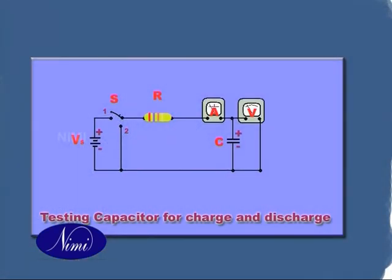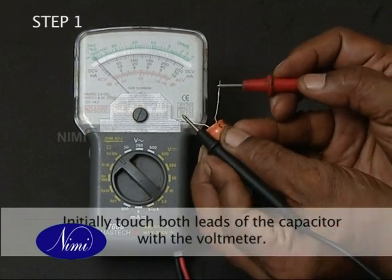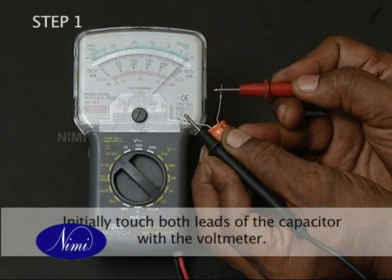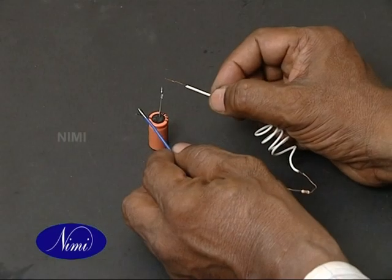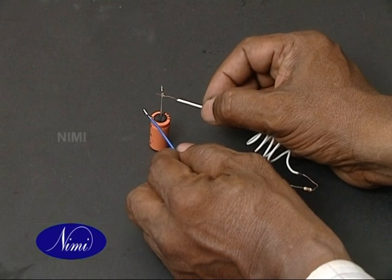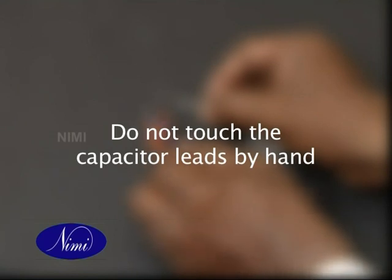Here we are going to see the procedure for testing the capacitor for charge and discharge. Initially, touch both leads of the capacitor with a voltmeter. If there is any deflection, contact both leads through a resistance for a sufficiently long time. Do not touch the capacitor leads by hand. The high voltage retained by a charged capacitor will give a shock.